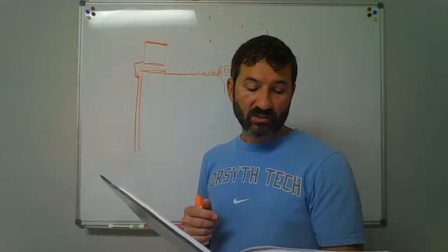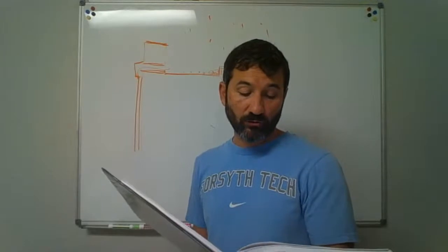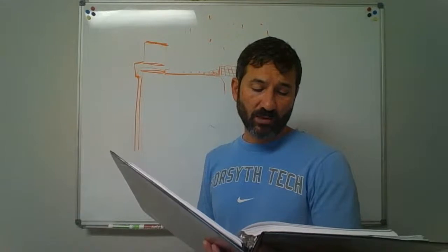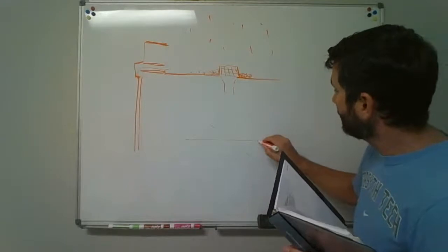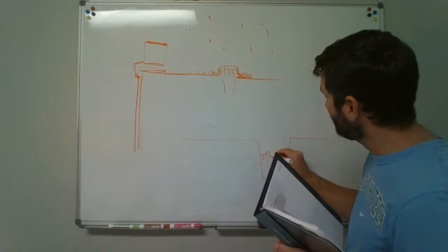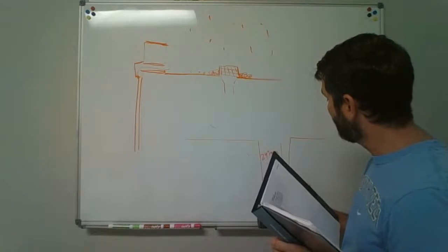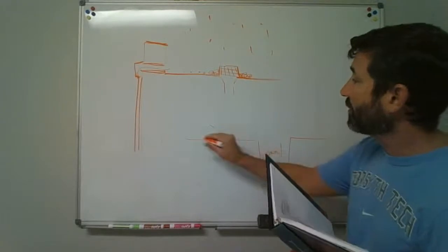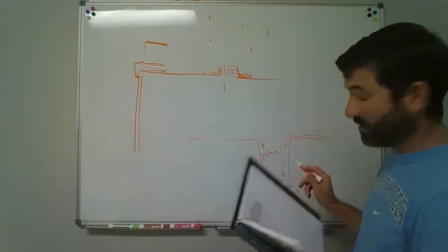The pit shall be not less than 18 inches in diameter and not less than 24 inches deep, unless otherwise approved. The pit shall be accessible and located such that all the drainage flows into the pit by gravity. Which makes sense, if you're collecting it. It says no less than 24 inches minimum deep, 18 inches minimum wide, and then all this area, if water is going to get here, it will run and drain into here. Okay.